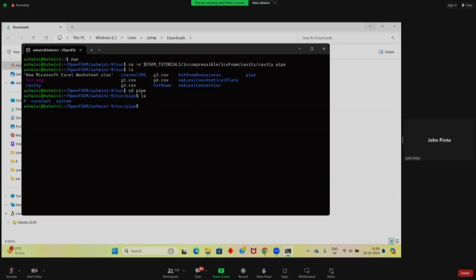If we are trying to do the block mesh, then we'll be changing certain things, right? We'll be renaming the patches, walls, and the boundary conditions we have not yet defined. So at present, we do not need the 0 folder. So we'll be renaming it. To rename, I'll type the command mv. I'll rename 0 to 0.orig. This command will rename the 0 folder to 0.orig. Now my 0 folder is renamed to 0.orig.